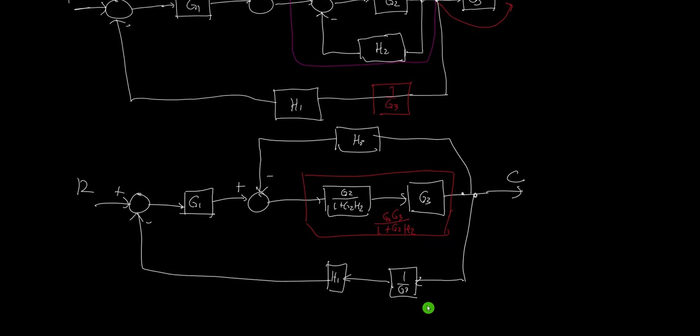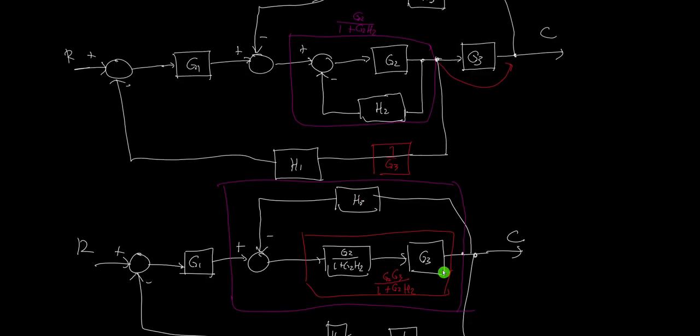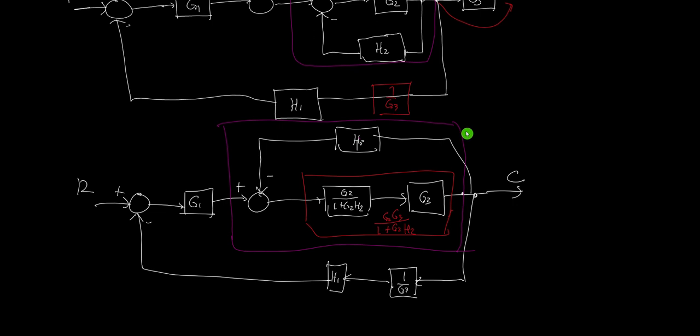Then the next thing that I will be doing will be this part. So combine them, they are in parallel. Or is it parallel? It's not parallel because the summing point actually is on the left side. It's not at the right side. So we can just move H3 at the bottom, then it's a canonical form. It's actually a canonical form. It's not a parallel block. So it's a canonical form with G. This is our G, and our H is this one.